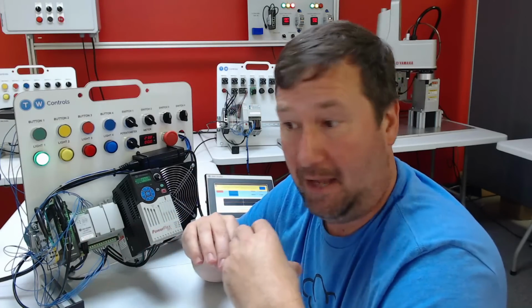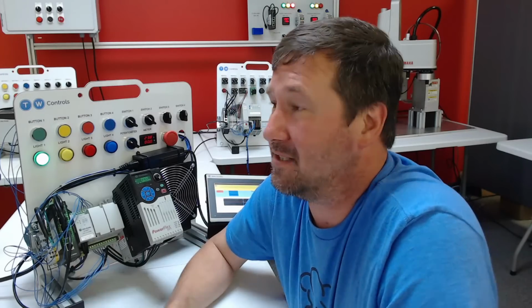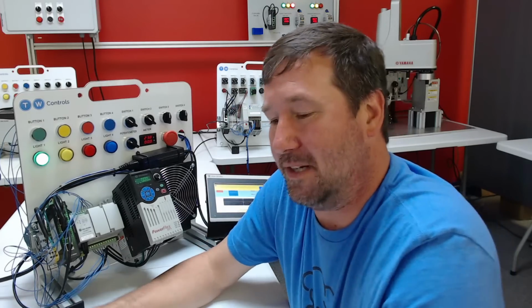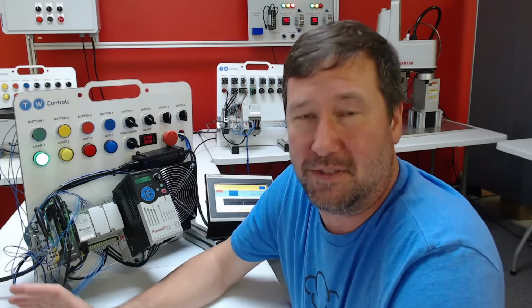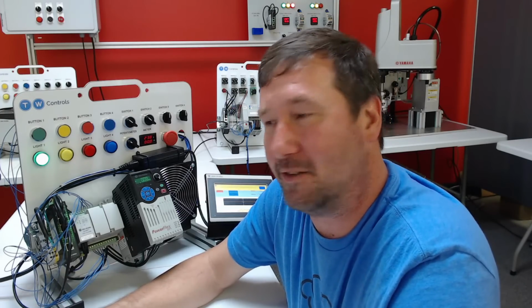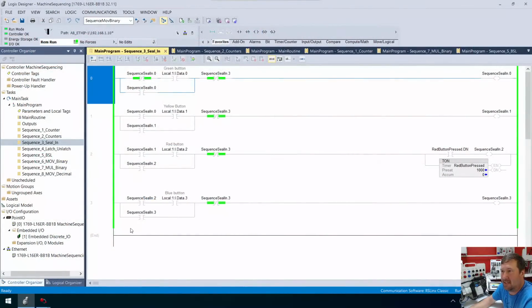Now, flat out, you cannot do math or anything like that any more efficiently than structured text. And let's face it, a compute statement in ladder, isn't that structured text? So already there's a lot of sprinkling of structured text, but where I usually draw the line is when we're actually dealing with physical inputs and outputs. I think at that point you need to transition to something else just to make it a little easier to troubleshoot. But okay, let's get back here.